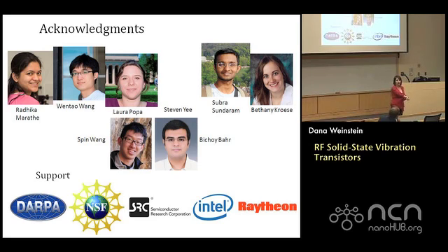Bichoy here is working on both taping out the real devices, but also simulating and optimizing them. And there are ways for us to predict those loss mechanisms into the substrate, and also the signal crosstalk between them. So that's something that we can develop. You can play around with things like deep N wells, and there's ways to get better isolation, both electrically and mechanically, as needed.